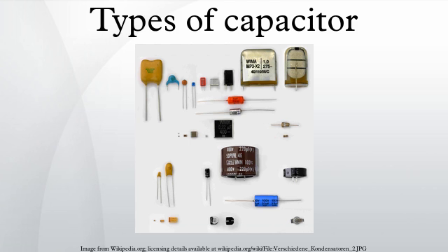While existing supercapacitors have energy densities that are approximately 10% of a conventional battery, their power density is generally 10 to 100 times greater. Power density is defined as the product of energy density, multiplied by the speed at which the energy is delivered to the load. The greater power density results in much shorter charge-discharge cycles than a battery is capable of, and a greater tolerance for numerous charge-discharge cycles. This makes them well suited for parallel connection with batteries, and may improve battery performance in terms of power density.